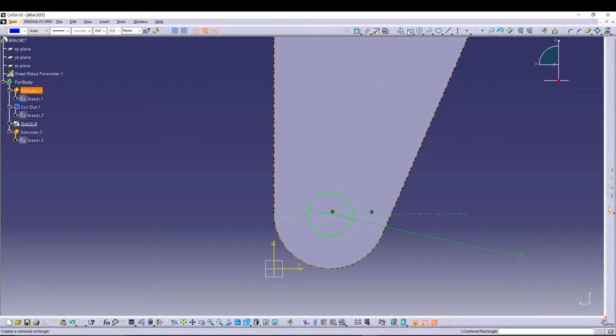After that, I can do one rectangle. Let's go for rectangle like this. Make sure it's not construction. Let's go for an axis from the center. Go for constraint. These 2.5. Select these two again. Right click, allow symmetry line and axis. So that I can select the top edge and this axis. Say 6. Right.